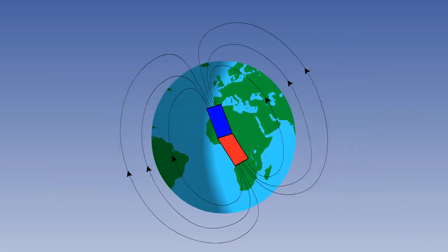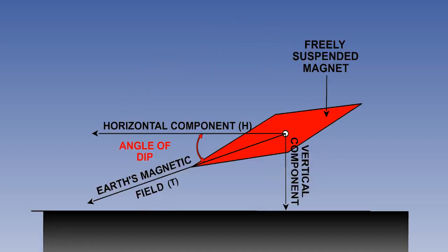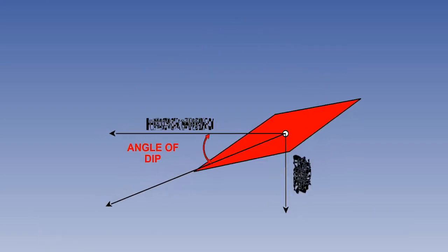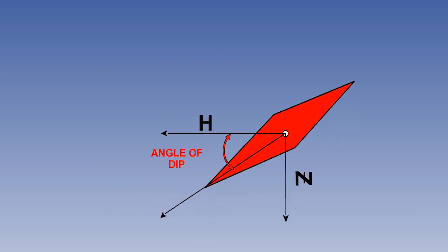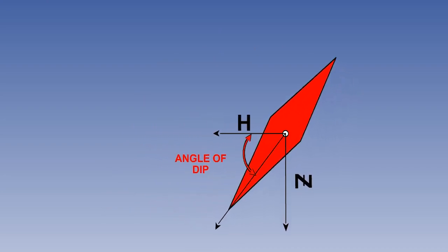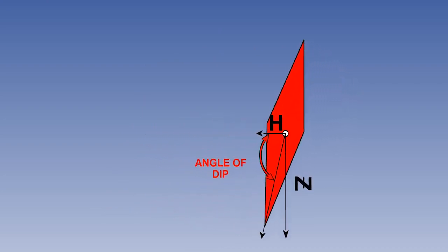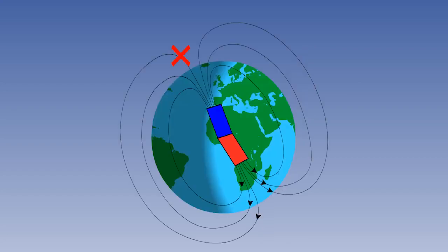If grid technique is being used because of the problem of meridian convergence at high latitudes, then the aircraft may also be near to one of the Earth's magnetic poles. If so, it may not be practicable to use a magnetic compass because variation may be changing too rapidly, or the horizontal magnetic field strength may be too weak. However, even at high latitudes, this may not always be the case.